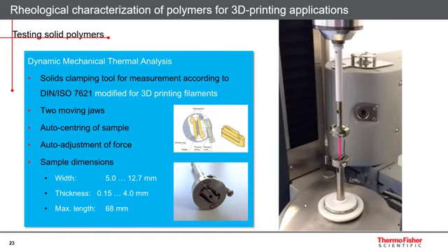The obtained data is used to identify characteristic phase transition temperatures, such as the glass transition or the occurrence of melting and/or crystallization. In addition, DMTA can be used to determine final product performance and to interrogate relevant application-based properties, such as stiffness, brittleness, damping, or impact resistance.